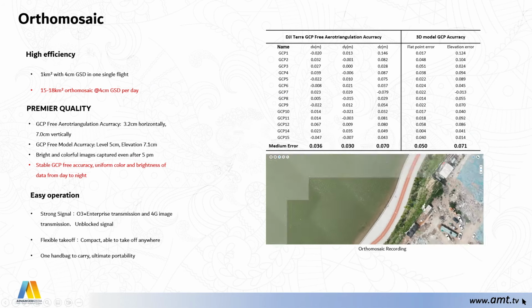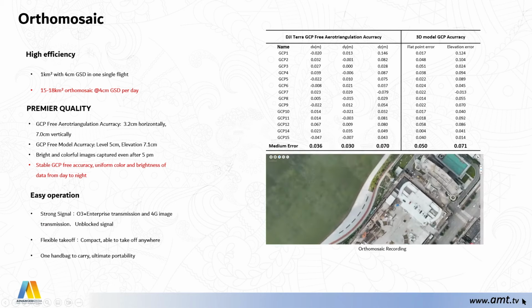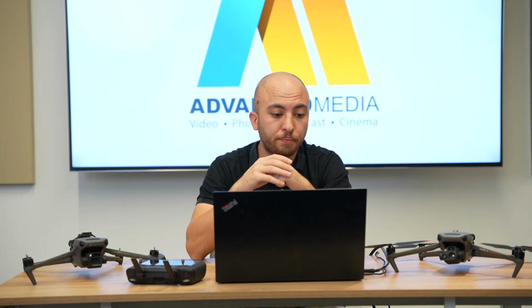GCP-free, without using any ground control point, we achieved 3.2 centimeter horizontal accuracy and around 7 centimeters vertical accuracy, without using any GCP or ground control point.